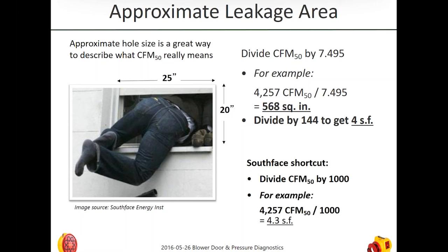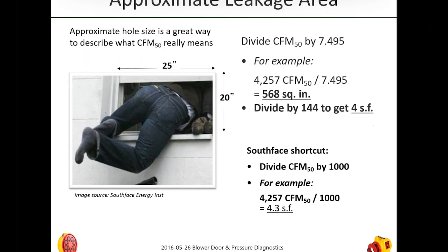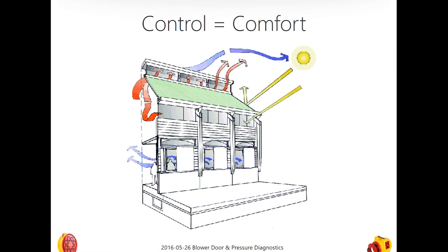Someone was asking me about passive house leakage, and I just did a calculation for a 10,000 cubic foot house, which would be about 1,200 square feet. The maximum allowable leakage is 100 CFM, which is amazing when you consider that passive house requires the entire house to leak less than the duct systems we have, which can often leak over 100 CFM. So passive house technology can get the entire house down to less than 100 CFM at 50 pascals.